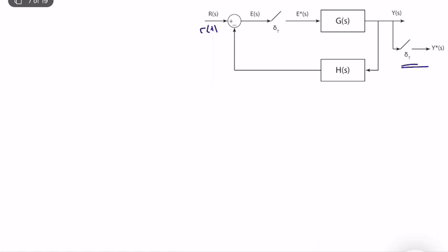can see, this sampling is somewhat separate from the feedback block. It can happen, it may not happen. It changes from system to system. Y of S is multiplied with an H of S continuous time transfer function, and we subtract it from R of S. Let's say this is F of S, to obtain E of S. We have an error signal between our measurement and our filtered output. This is generally a filter, and it can be a continuous time filter.